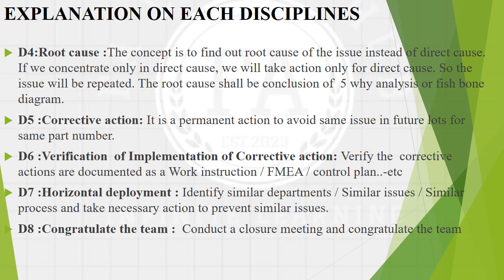So why did he do only marking and not permanent scratching? The cause may be that our system procedure or SOP for testing, or any instruction, was not provided to the operator or testing inspector to do permanent scratching or permanent damage on defective or test-failed harnesses.